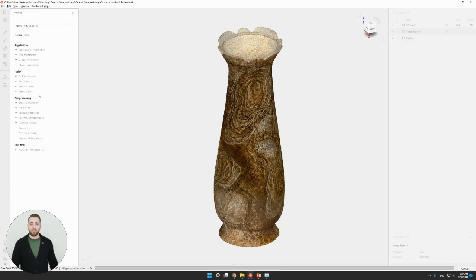As you might have noticed, there were a couple of settings for the algorithm. So now let's go over all of them and see what they do. In most cases, we can get away with using default settings, but sometimes you might want to change them depending on the project that you're working on. The first setting was pre-process images, and this setting helps you to get more contrasted pictures in case of dark texture. So you're supposed to turn it on when taking pictures from afar or when the texture of the object is rather dark.